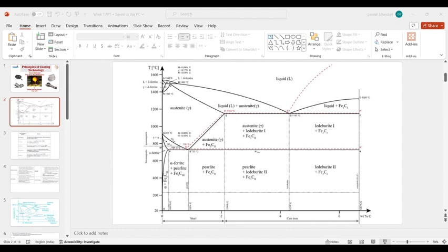If we heat treat our mild steel above this temperature, we are going to get stable austenite. Here, why are we taking this line as straight? We are talking about eutectoid steel having 0.8% carbon. We are only talking about eutectoid steel as of now, with 0.8% carbon.